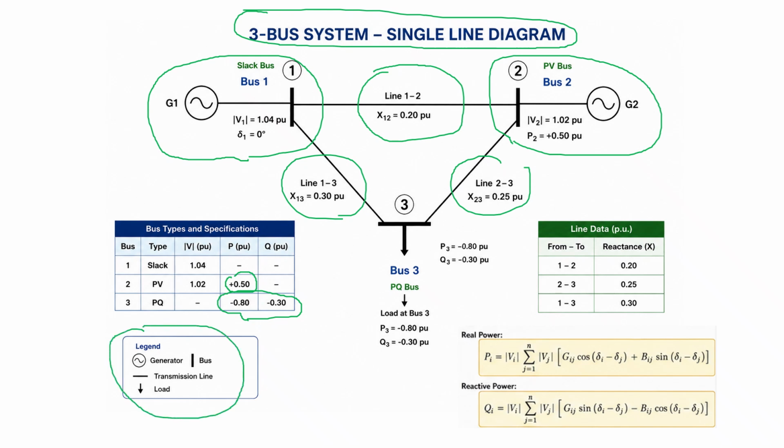So it's easy to remember the power equation for a finite bus or n bus. In our case, to make the calculation simple, we don't have a resistive part of both the generator internal impedance as well as the transmission line. We ignore that. So for our equation for active power, we can ignore this part because we don't have any conductance. We ignore it for simplicity. Again, for reactive power also, we don't have a conductance part. So the equation is reduced to this representation.